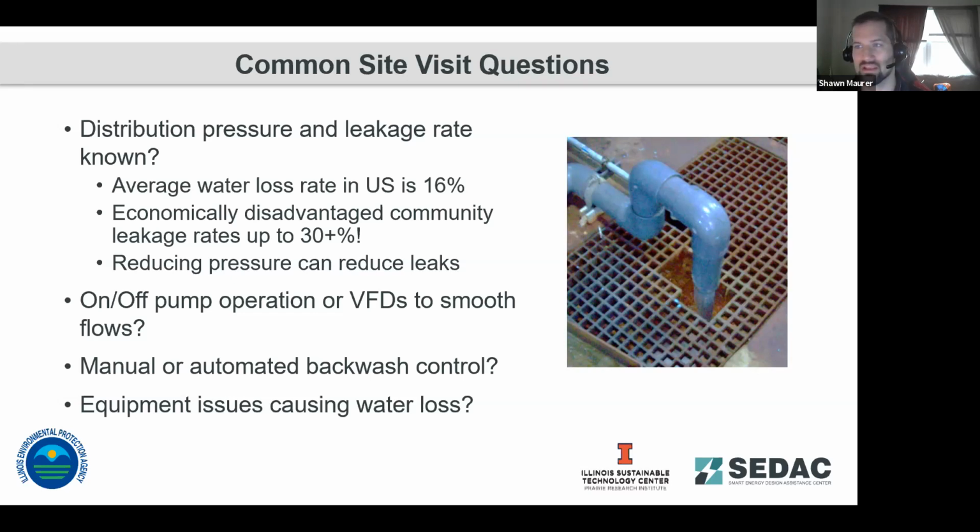And again, what we're looking at there is minimizing how much wastewater is coming out of the plant, maximizing how much throughput you have, so that minimizes your initial raw water pumping. And again, that ties back into, if you're minimizing how much water you have to pump, you're also saving how much energy you're going to be spending on pumping that water.